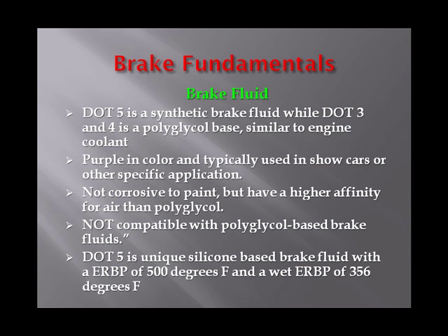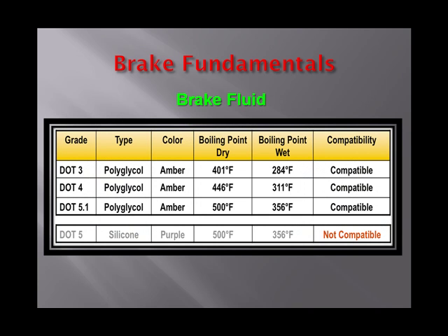DOT5 is a unique silicone-based brake fluid with an equilibrium reflux boiling point, ERBP, of 500 degrees Fahrenheit and a wet ERBP of 356 degrees Fahrenheit. DOT3 is a conventional brake fluid with an ERBP of 401 degrees and a minimum wet ERBP of 284 degrees Fahrenheit.